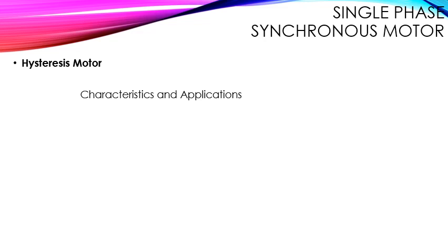The rotor with no windings or teeth makes the motor operation quiet. There are no mechanical and magnetic vibrations, and that's why there is noiseless operation due to resilient mountings, right? So because of the ability of noiseless operation and to drive high inertia loads, the hysteresis motors are suited to drive timing devices, electric clocks and other precision audio equipment.